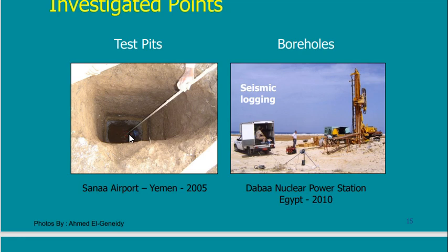We can just go one floor or 2 floors maximum, but they can build houses using this clay, and they can drill holes that can reach very deep inside the ground. But usually, if I do a test pit, it will be something like 2 meters, 3 meters maximum. Don't depend on more than that. But with a machine like this, I can go 50, 60, 100, similar to this one. So this is the test pit, this is a borehole.